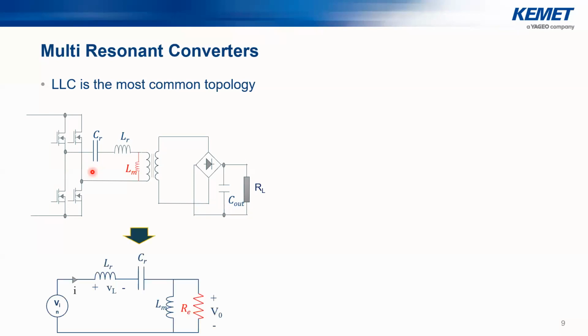So how will this help in enhancing the load control and the frequency issue that we have seen previously? Let's first see the equivalent circuit of the LLC topology. Again, we can make the same assumption that we made previously for the LC series power converter.